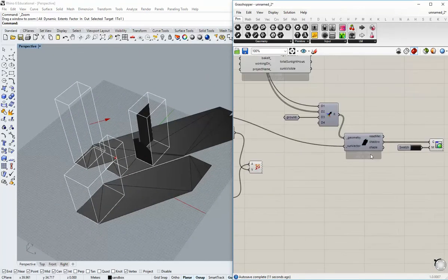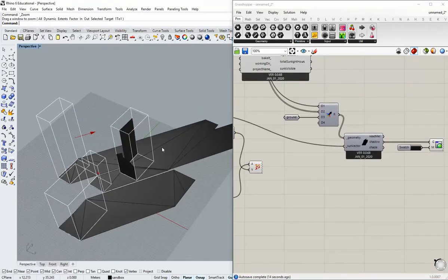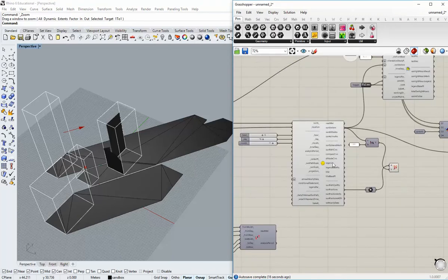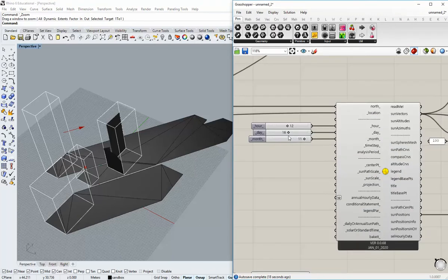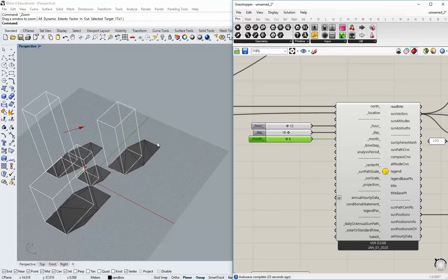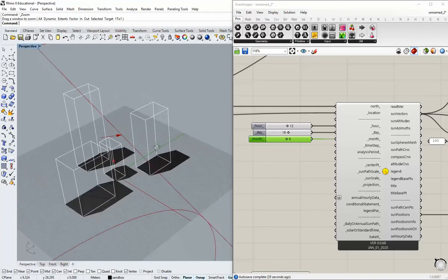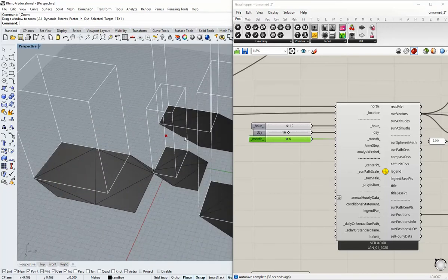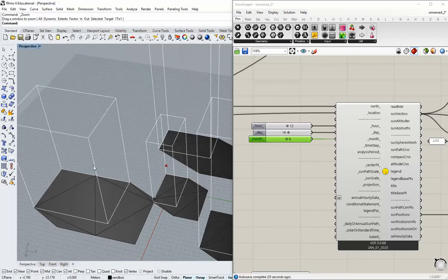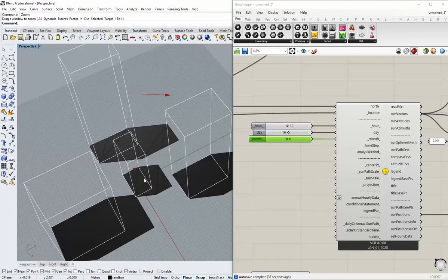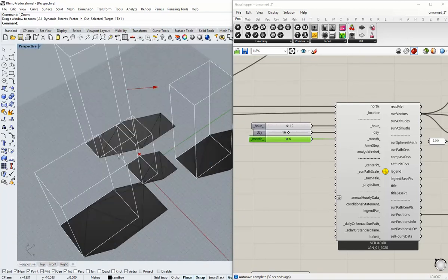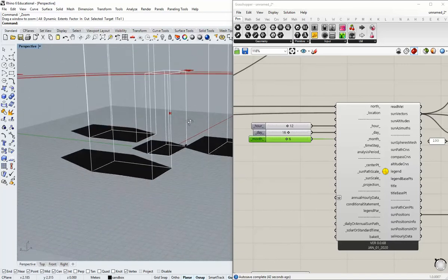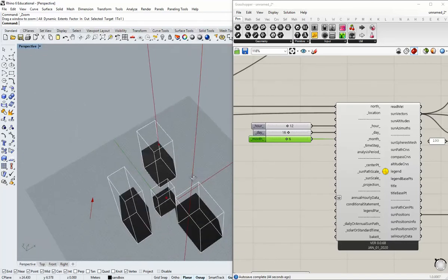Now again, if you make a shift to the angle of the sun, this should update. So I'm going to right-click or double-click on this and make this June and hit OK. And now we're updating our sun angles here. So it's much higher in the sky, and the buildings are going to catch a lot more sun, and they're going to cast shadow a lot less on one another. So this, in conjunction with the other analyses, is going to give you a good idea of how much solar radiation is really going to be happening here, which in this case in June is going to be quite a bit.